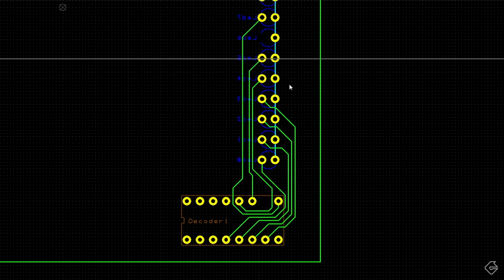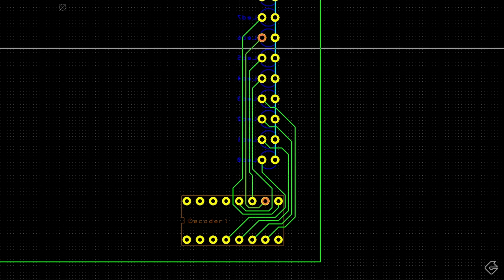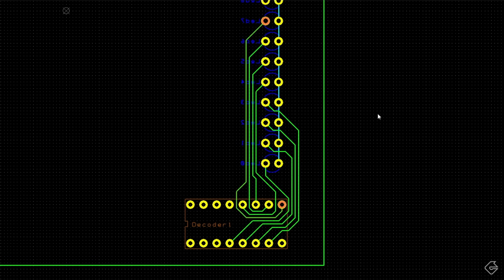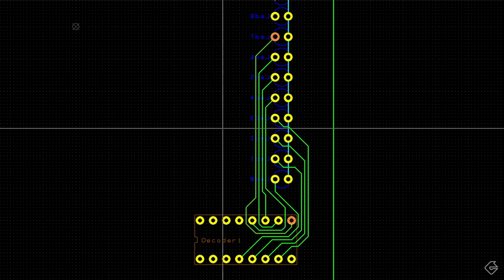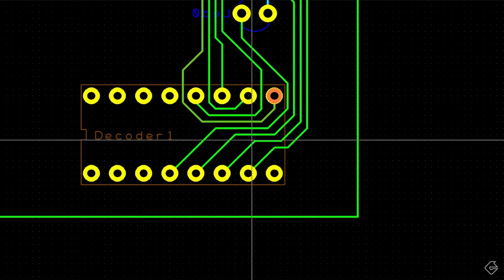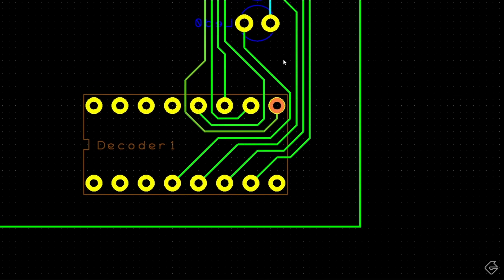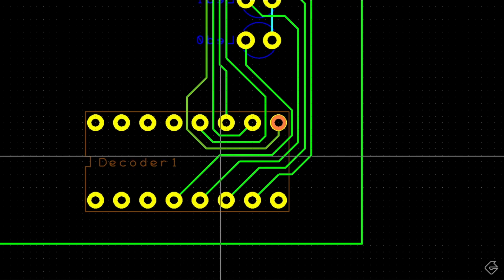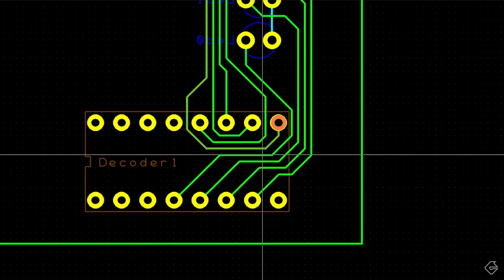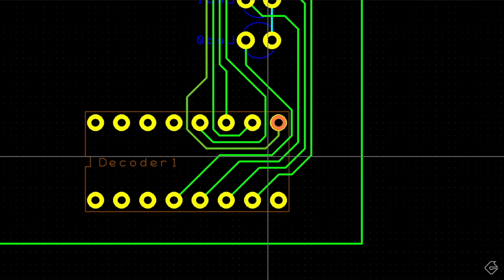So drawing these traces in your PCB software, the way to do that depends on, well, your PCB software. In this one in particular, it's actually very easy to draw. You'll notice that I try to avoid right angles where possible. So anytime there's a trace, I just try to avoid a right angle. I've read in places that it's better for the electronics.